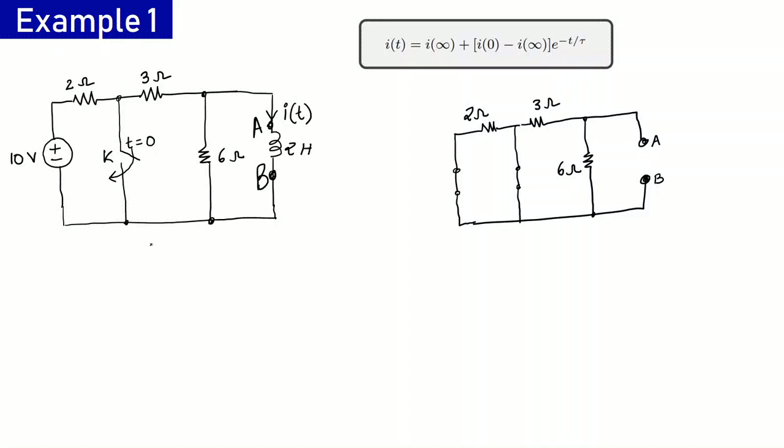To deactivate it, we see that here there is a voltage source, so I have replaced the voltage source with a short circuit. To calculate the Thevenin's equivalent resistance, I will see the resistance across these two terminals.